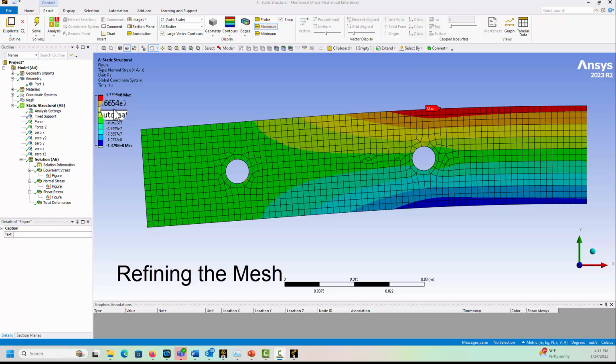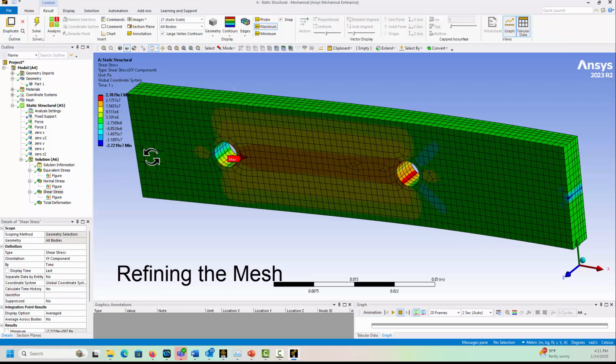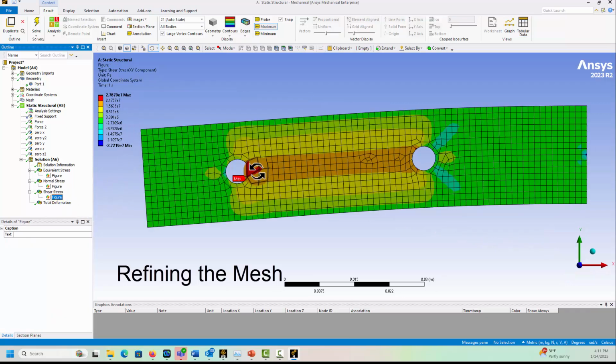So the only other thing I might check is to look, for example, at the shear stresses, and in terms of the magnitude, there are some more local things happening around the shear stresses. If I really needed to get the maximum around these holes, I'm probably going to need to refine it more, because you see these stresses have some sharp gradients across one element. And we also see a little peak there. However, our main goal is just looking at patterns on this.